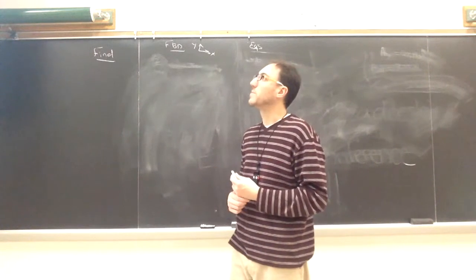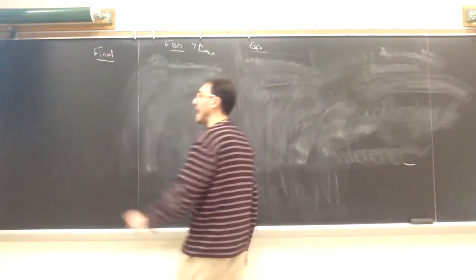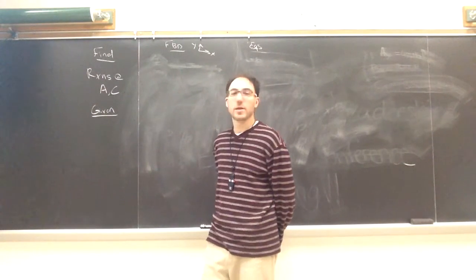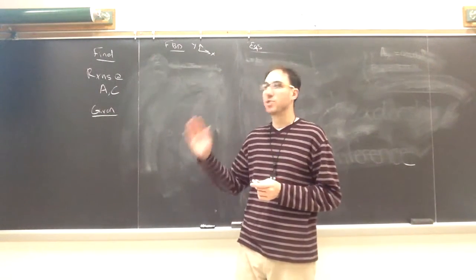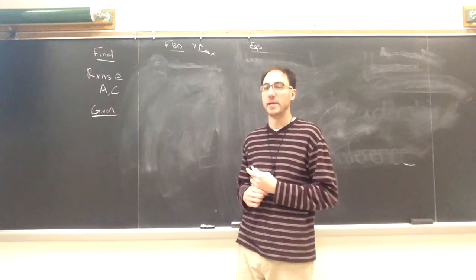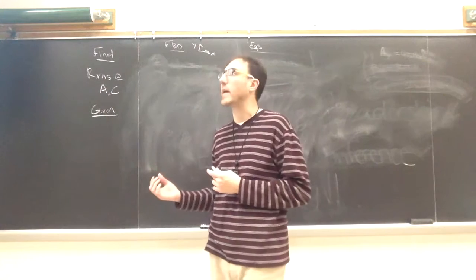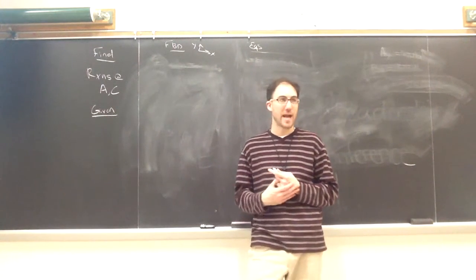What we want to find ultimately is the reaction at the pin at A, and now we have a fixed support at C. Again, looking at it from the perspective of chapter 5, we're going to have 2 unknowns at A because it's a pin. And at the fixed support at C, we'll actually have 3 unknowns because it can't rotate, it can't move in the X, it can't move in the Y. A total of 5 external reactions.